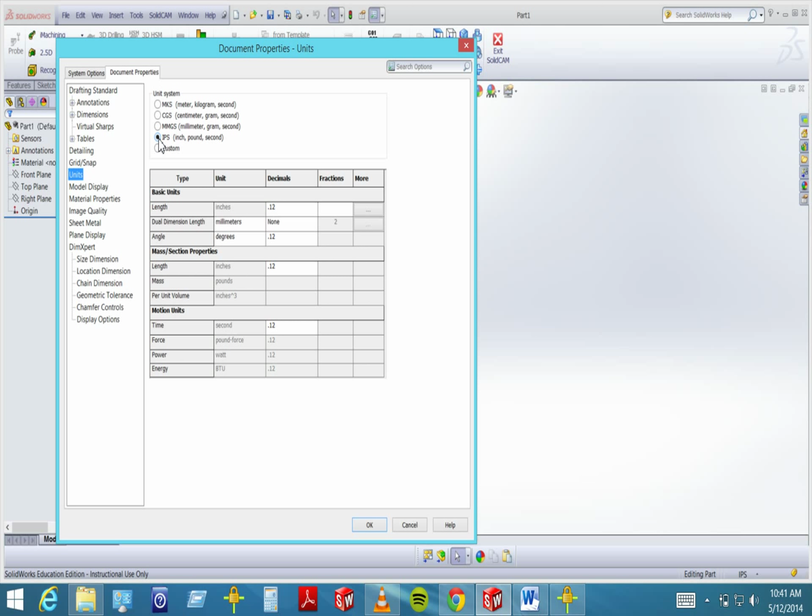You get all that stuff, and you need to know how to convert from one to another, and you need to know when it makes sense in your CAD models to call out a 1/4-20 bolt rather than an M4 bolt, because it's cheaper and faster for me to buy the 1/4 inch bolt. Now in your CAD model, you can just take the 1/4 inch and convert it to its metric equivalent. But when you go to your drawing and your purchasing, a lot of times you're going to want to be in imperial units, and it's up to you to know which.